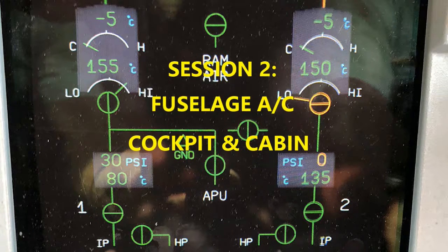All right, just a reminder, what's the function of the air conditioning packs? Their job is to reduce the temperature of the bleed air from the pneumatic system, coming off the main engines or the APU. And then what's it going to do? It's going to distribute that conditioned, cooled down air into the cabin. It's also going to reduce any water that's in the hot bleed air. And this is where we're going to get into some of the components I just mentioned. So what makes up all of this? I mentioned the water extractor and all that.